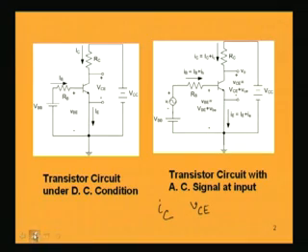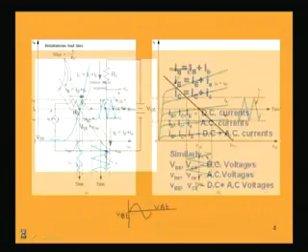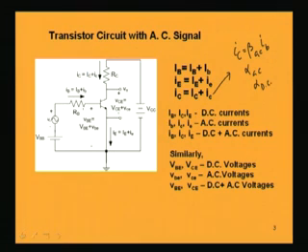In this graph both are shown. This is the biasing voltage, but this is the voltage between base and emitter, and this is the corresponding base current. Now, in the input circuit, the DC load line can be drawn by connecting the maximum and minimum values on the x and y axis, for a particular RB, because if we change the value of RB, our load line will differ.